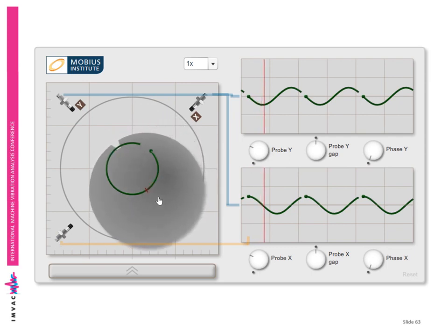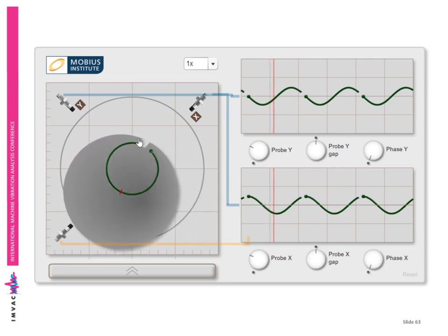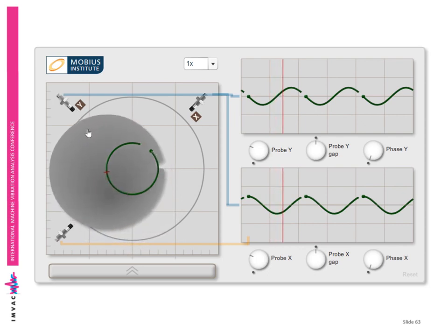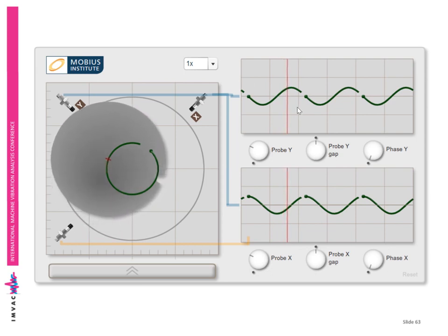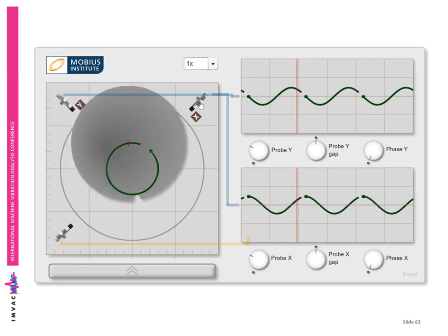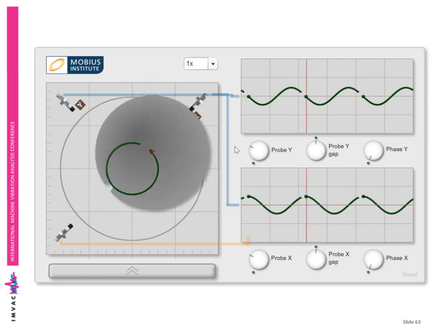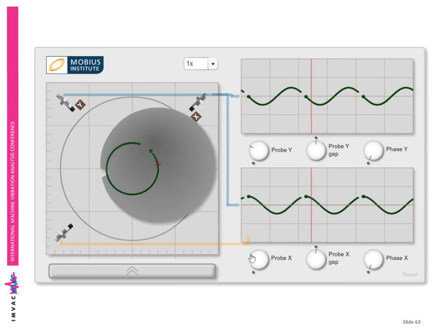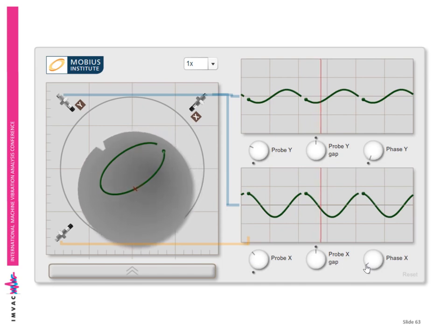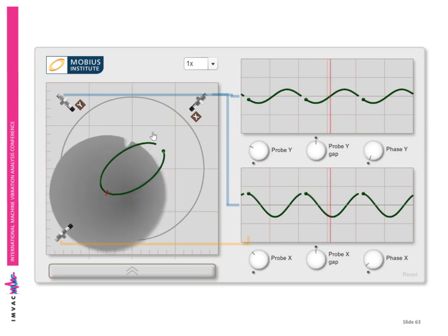But basically, as the shaft turns, the key phaser sees the keyway, or maybe a key in actual fact. The two probes monitor the gap, which again is very exaggerated, but we end up with two sine waves, one from each probe, and we can plot them against each other. So X versus Y gives us this orbit, and we might find that, for example, there's more motion in the X-axis, and it wouldn't be an exact phase relationship, as in wouldn't be exactly 90 degrees phase, and we might see a bit of an elliptical motion.